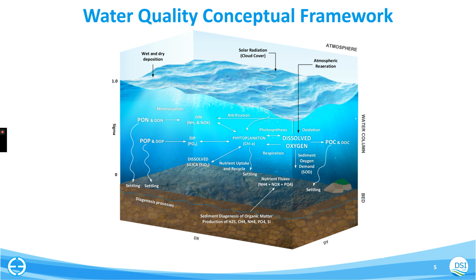But we found that the sediment diagenesis model works really well with some basic, relatively simple parameterizations. If you have total organic carbon in your sediment bed at a number of places, using that and standard ratios between organic carbon, organic nitrogen, and organic phosphorus, the Redfield ratios, you can estimate your major drivers in your sediment bed for your initial conditions.